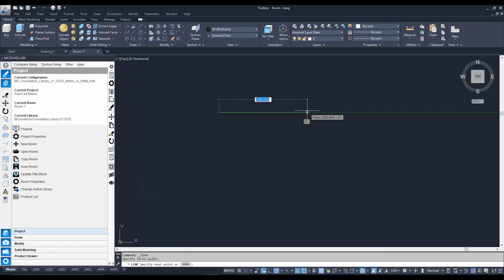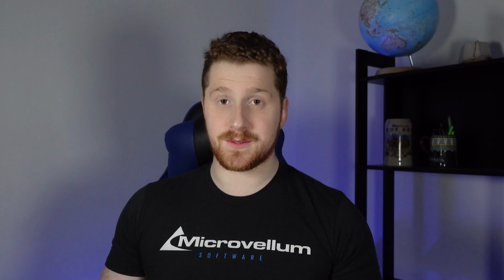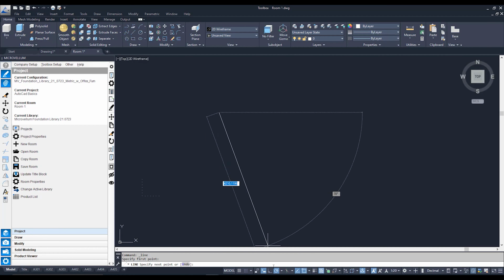Now you can see that I can move my line in a 360 direction, but at certain points, mainly 90 degrees, a green line appears. Now this green line is designed to make it easy for me to snap onto my 90-degree angles. And here it's turned on by this little button down below here. Alternatively, you can click next to it to select ortho mode. Clicking on this has it automatically come in, no matter where you move your mouse, to be 90 degrees.